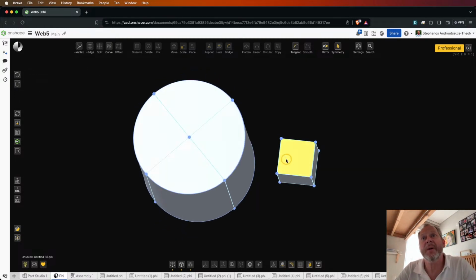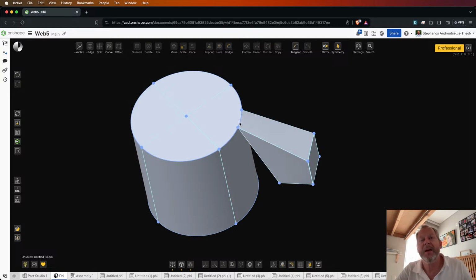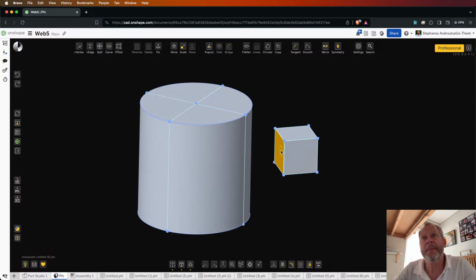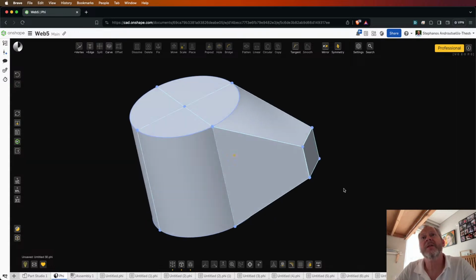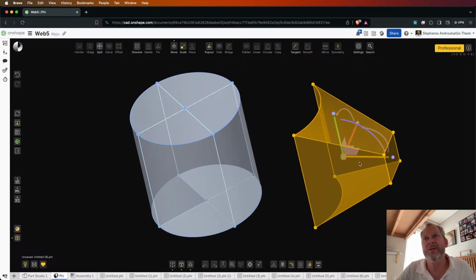And I can do it again, but again, in this case, I will have the shift, I will hit snap, and then I will have the shift button pressed. And in this case, the edge also snapped, but instead of capturing the entire length of my target edge, it only snapped onto the part of the edge that corresponds to it geometrically. And finally, I can have a face. I can hit snap, and then a target face, and my face deforms in its entirety to match the target